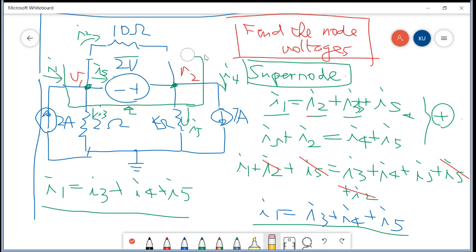Draw the box a little bit larger. You can draw this box a little bit larger like this, because actually this 10 ohm resistor is in parallel with this one. The resistors connect to the same point here. So the current going in this path and that path always cancel for that supernode.